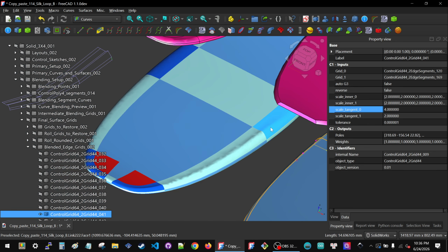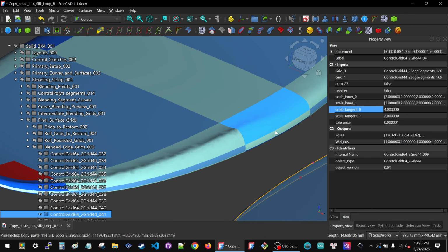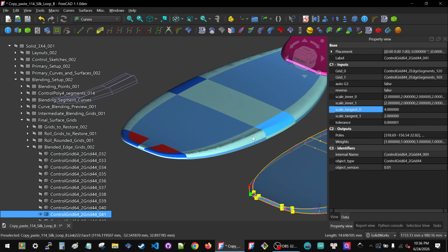And this effect travels into the adjacent double blends, but it does more than that. It actually breaks the tangency of this double blend to this guy. If I wanted this to work, I would have to do it on this guy as well. So that's a bad idea in general, almost never what you want to do.